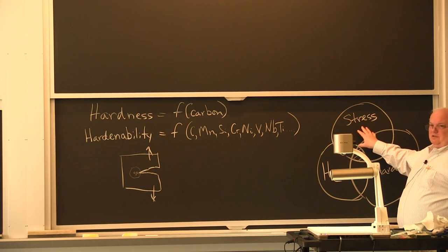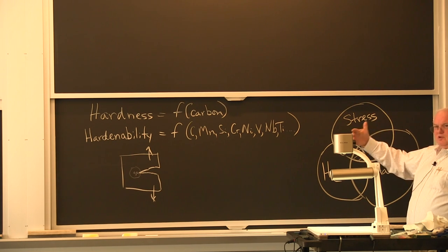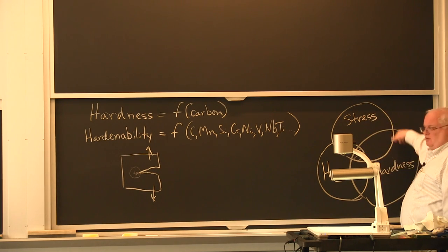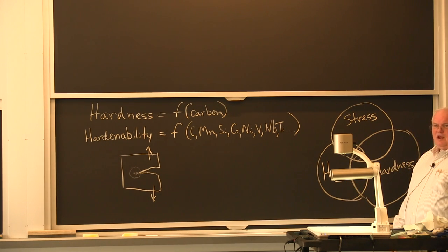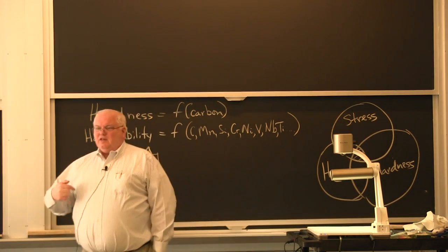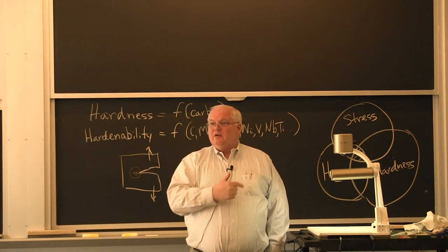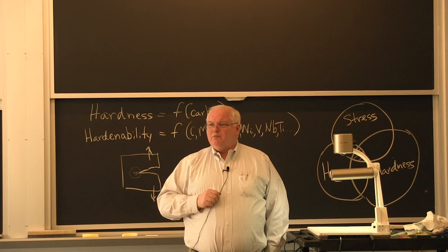It's the high strength steels, the things we use for nuclear submarines, for bridges when we want to save weight and we're using 100 KSI steel. You never would weld on an aircraft landing gear, okay, forbidden. 250 KSI steel, I mean, you've got a huge stress circle there. The only thing you can do is get rid of the other two things. So you've got to get rid of at least one of these, and the higher the strength of the steel, the more you have to be careful about working on several approaches to avoiding hydrogen cracking.